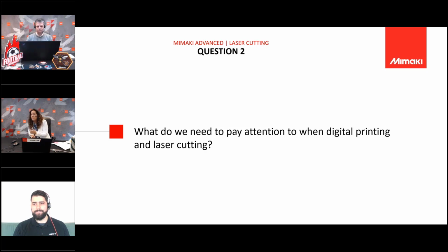What do you think needs extra attention on this particular part? For laser cutting, and especially in combination with ink, you need to know if you're cutting through the ink or not. So the type of ink that you choose is important. There are hard substrate inks, but also flexible inks. I think we will come back to that a little bit later. But if you're going through some inks, you can cut through and the ink will break, will go off. We will see a picture later on.